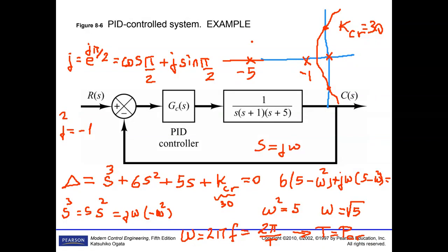You can just double click the scope and go to the settings. Number of inputs. We get 2 inputs, all right? And the other one you get from the input, right? You can now run it and compare both input signal and output signal. The one we just got from the input, the other one is the output. Now we can see the changes. This is your input step. The input is the signal which is 1 at one location and 0 in other locations. So this is your input, and this is how your system responds to its input.